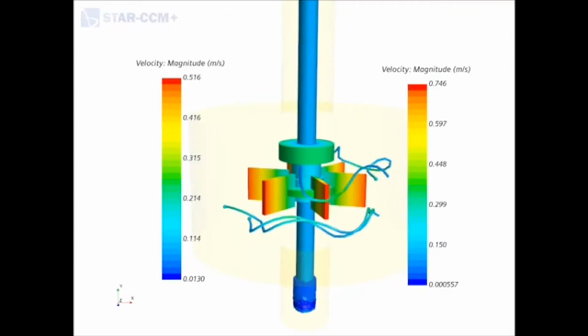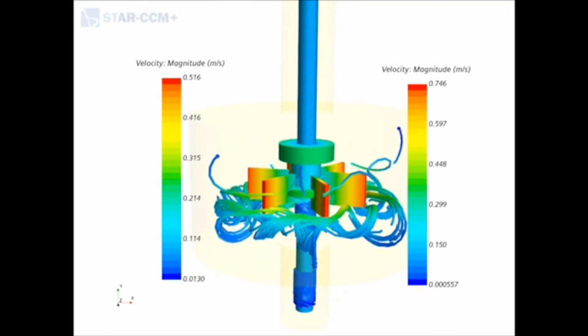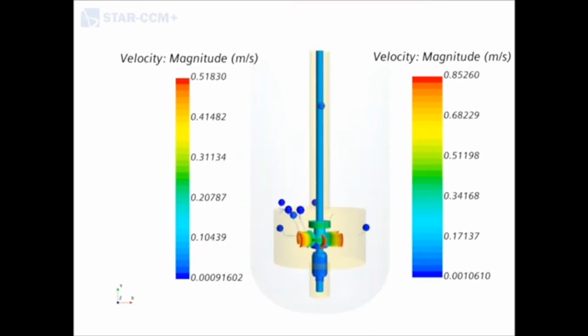In the Rushton's streamlined animation, the impeller produces a soft agitation, therefore the velocity outside the rotating volume is almost zero. On the other hand, the new design is similar to a Smith turbine because of the curvature of the paddles as shown on the animations. In comparison to the Rushton design, this impeller works as expected because it disperses more fluid because of the paddles' form.